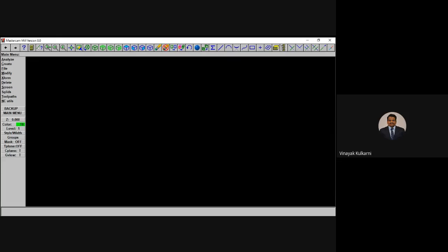If you have very expensive tools to be used or an expensive raw material, you cannot directly input the CNC program onto the CNC machine. If there is a loss of tool or breakage of the tool or even the breakage of the raw material, then it will be a huge loss to the company. So what we do is, we first put it into simulation software, check for the simulation, and then transfer the same program to the CNC machine.